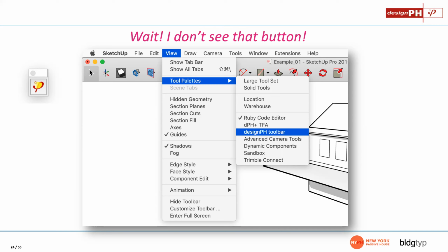That said, most contemporary energy modeling programs, think ComCheck, eQuest, any of those, do not have any ability to take into account psi-values. And it's been one of the frustrations that we've had with those more typical energy modeling programs, in particular, starting to build thermal bridging analysis into building codes, is because a lot of the software available doesn't allow you to enter those values. That's changing though. Some of the new versions are going to allow you to build those in.